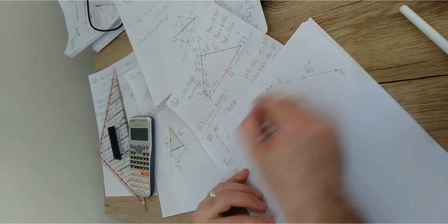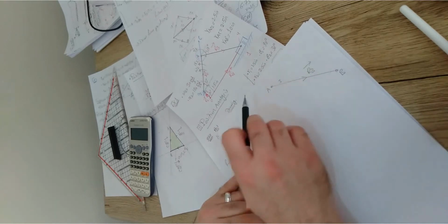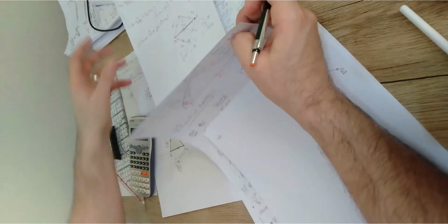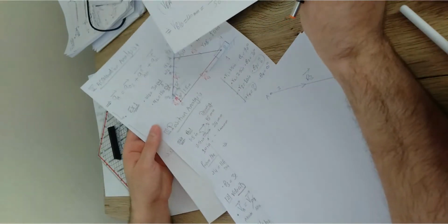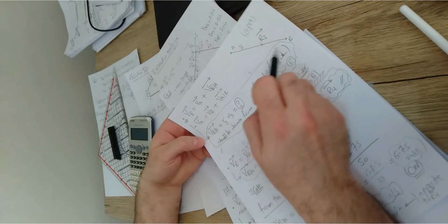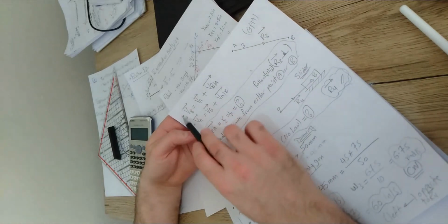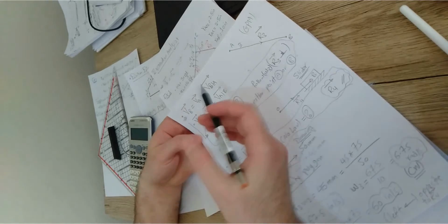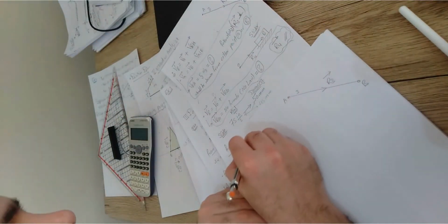And the equation for this link: you can refer A to B or B to A, it doesn't matter, it's going to end up with the same relation and the same result, but try to stick to what you already did for the velocity analysis. For the velocity analysis of this link, we used the first equation where we wrote the VB on the left side and the others on the right hand side. So we're going to do the same.